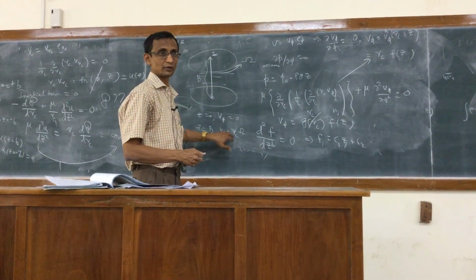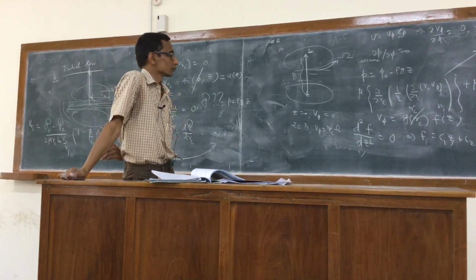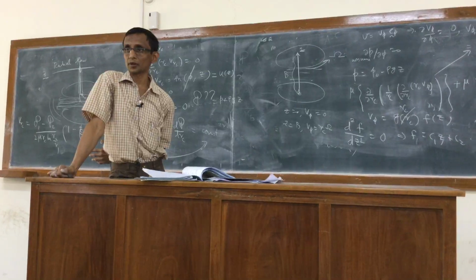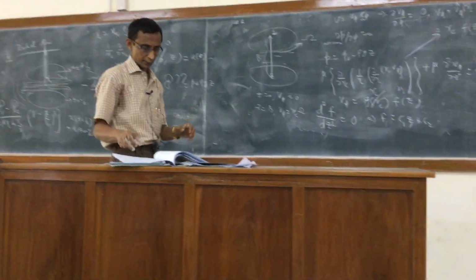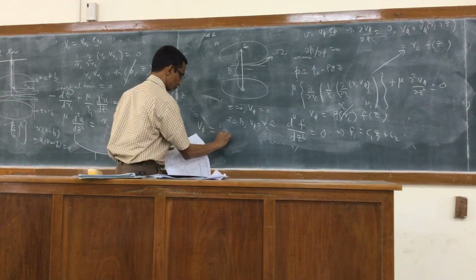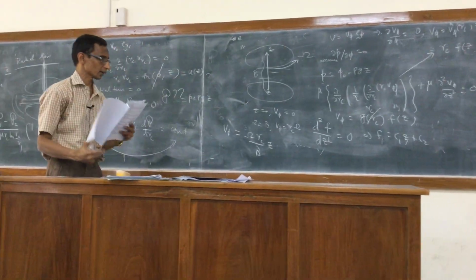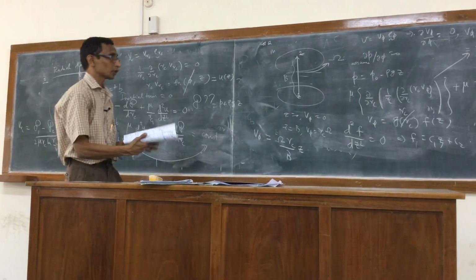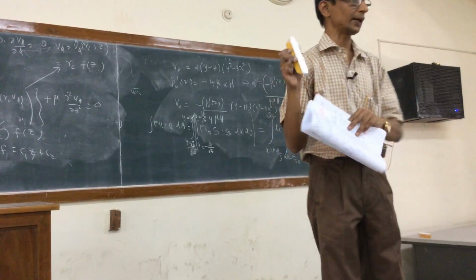He is probably inferring it from this form of the v_phi at the boundary. Right? That is one way of arguing why we should assume that form, or why that form is justified. But nevertheless, if you substitute this in, we will simply get a simple expression that v_phi is omega r_c by b times z, because the top plate is not stationary. Right?